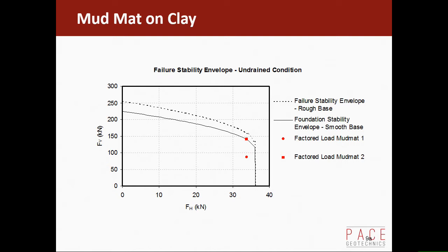What I would caution is you don't want to design a structure which is down there, because you don't have any weight in the structure to actually generate that. And it comes back to what I was saying yesterday, that clays can ultimately behave in a drained fashion, so you want a certain angle of friction to be developed to ensure that you do make your structure stable. I know that looks quite shallow, but if that's 50, that over there is about 45 degrees. In reality, that would be quite safe. The horizontal load is 33, say, but the actual weight on the structure there is 70. So you've got a factor of safety of 2 on the slide, or a coefficient of friction of greater than 0.5. So you'd be okay with that.